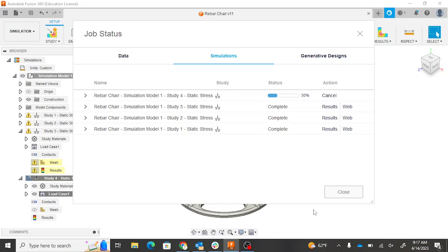And by default, it's going to load in newtons. That's not always helpful. In some cases, you need to measure in pounds or tons. The rebar chairs that we've designed in class are very simple, cheap products, and they're intended to carry pounds of force, not tons of force.